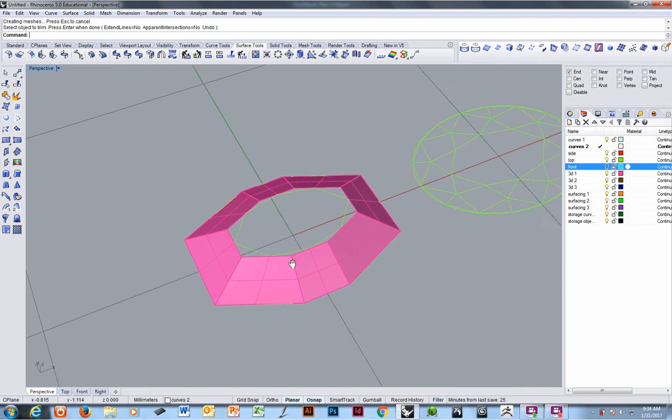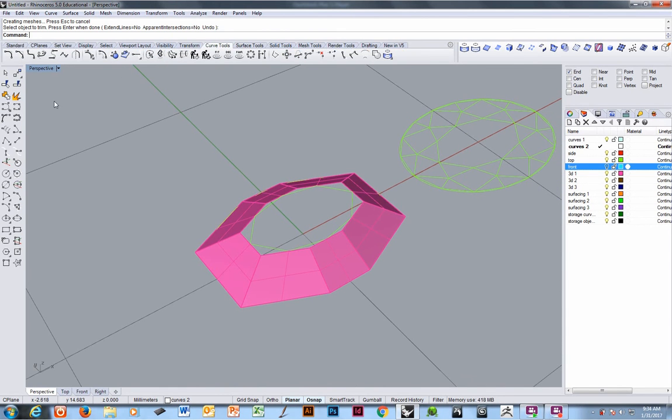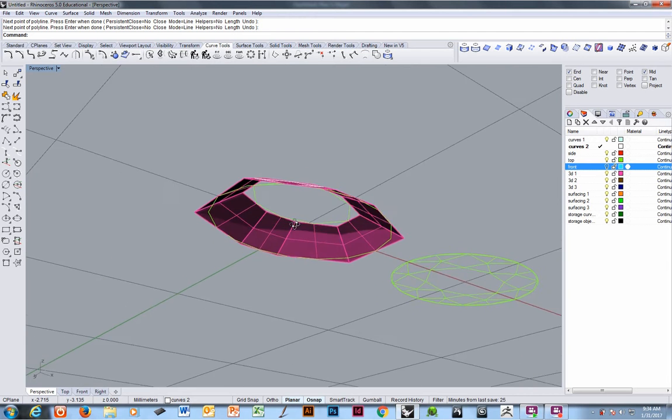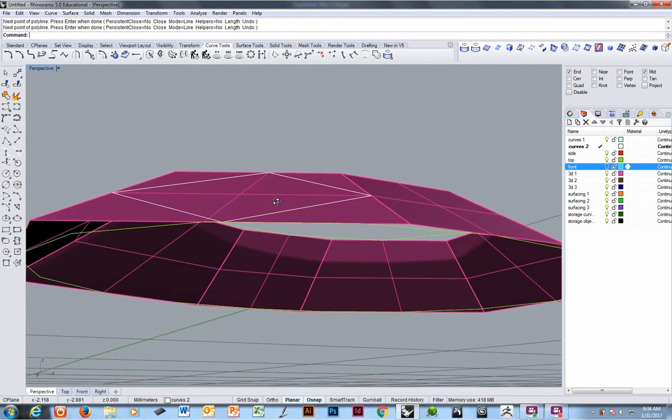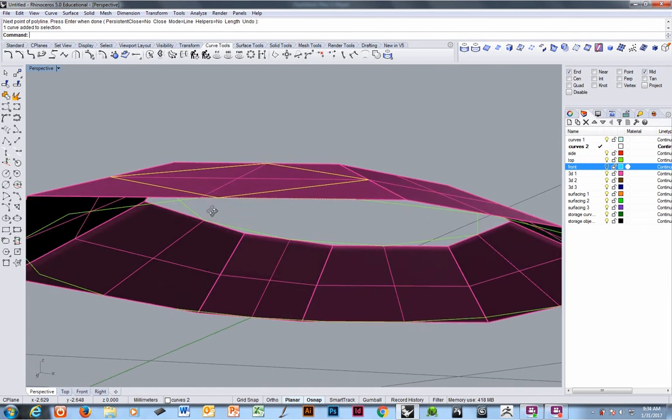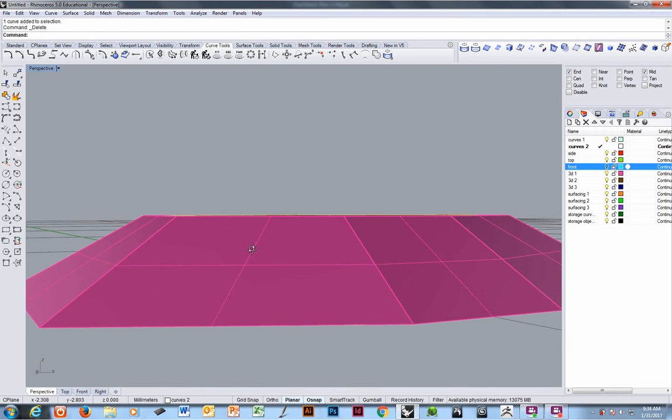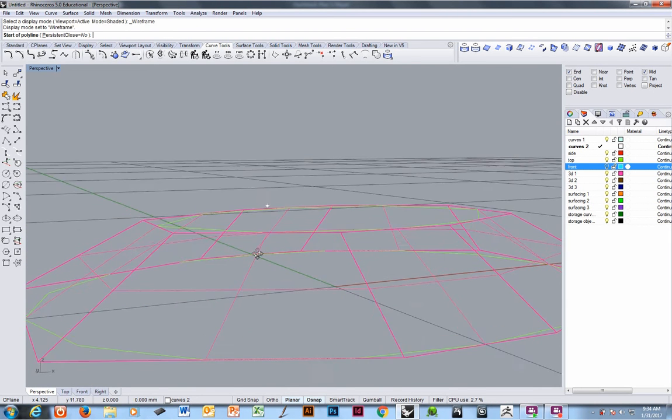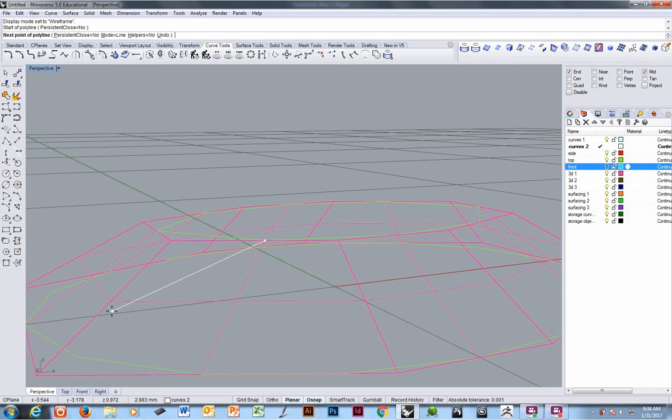now what I need to do is to draw the outline of the facet itself. Polycurve, using end and mid snap. It's important that that actually comes to the point. So, I need to redraw that. Go into wireframe so I can see end, mid, end, mid, end.